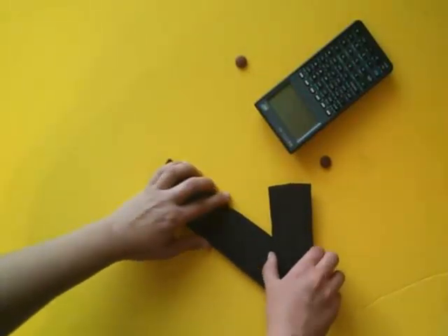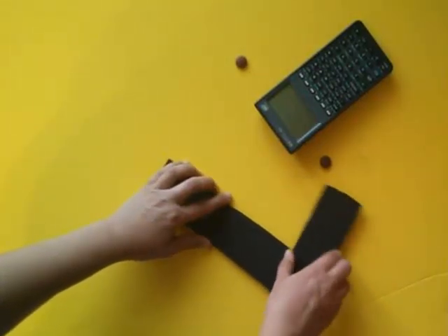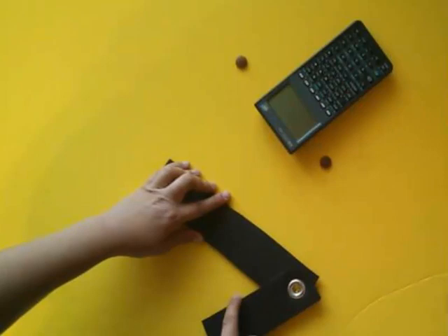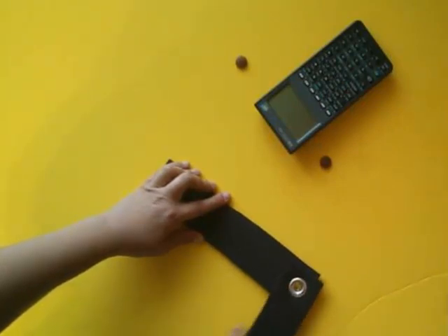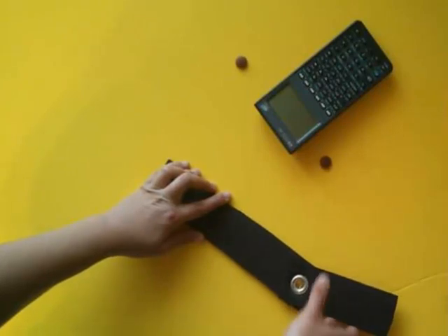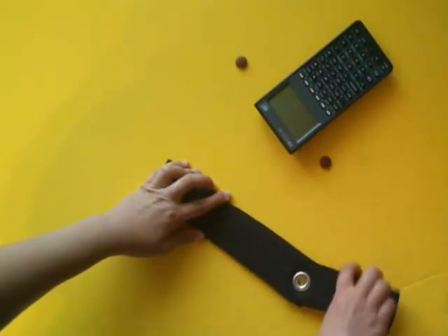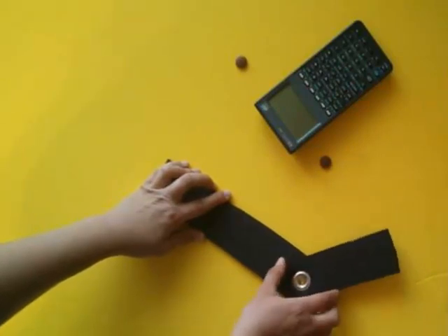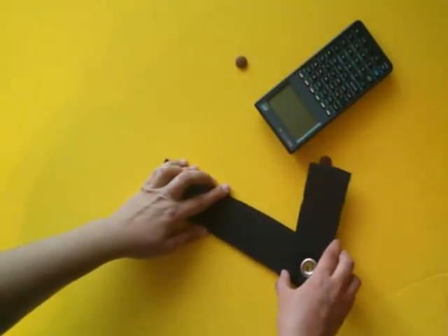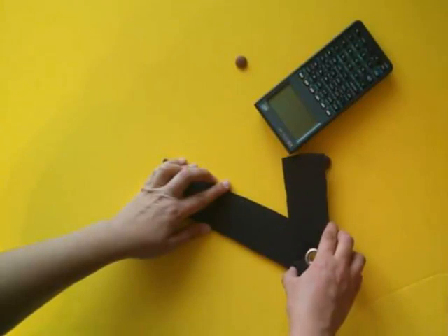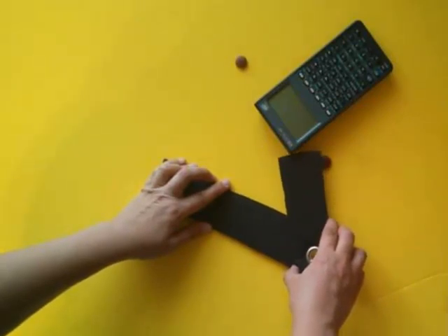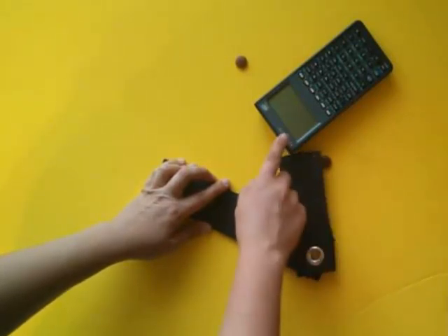I know that the second link moves in a circle around the joint axis. So I'm going to imagine that there's a circle drawn around this center point, and I'm going to move the first joint until that circle intersects with any point of my obstacle.